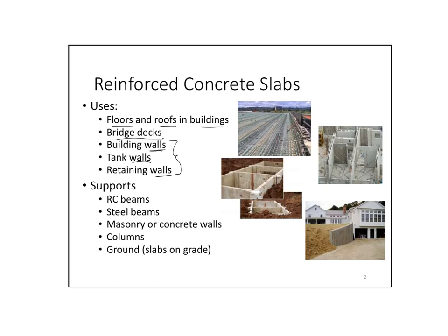Pretty much the same as when we look at walls in the out-of-plane direction of the wall. Whenever you're looking at a wall in this direction, it's like you're looking at a slab. Same exact design, but not necessarily the same exact specifications.